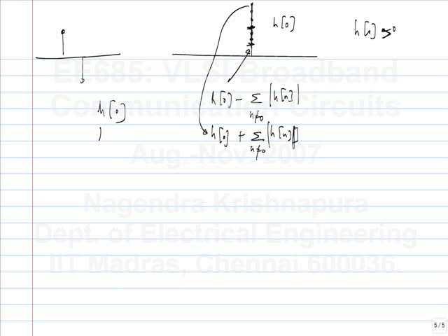But then let's say we add the remaining parts of H of n to the response. So now we have intersymbol interference. Now corresponding to a +1 symbol that was transmitted, you could get something less than H of 0, you could also get something more than H of 0. The minimum value is H of 0 minus this part, and this should be sufficiently above 0 so that it overcomes noise and gives you the desired bit error rate for error-free transmission.